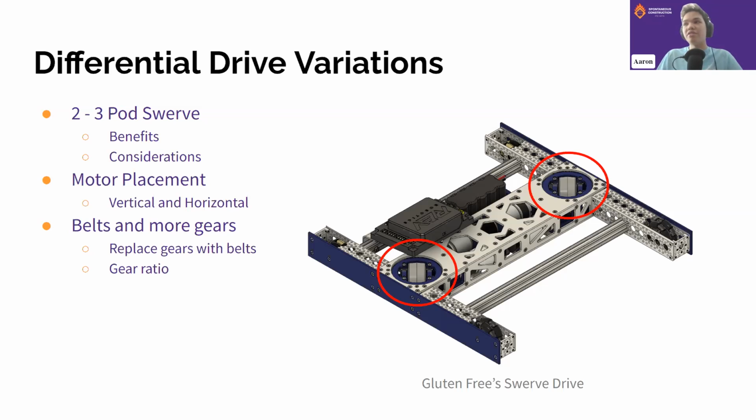It is also worth mentioning, though, that dead wheel odometry isn't the only way to localize outside of motor encoder odometry. Options like VI Slam, which was a webcam you could use to detect movement of the robot, seem to be fairly effective. I haven't used it myself, but I've heard it's good. Additionally, using cameras to recognize the site images is fairly effective. And in a game like this year, you can use the distance sensors to detect the junctions, which is a good way to keep track of where the robot is in case there is some sort of slippage.